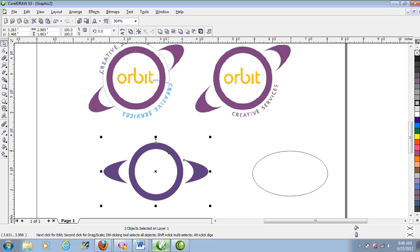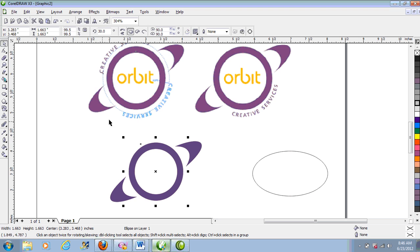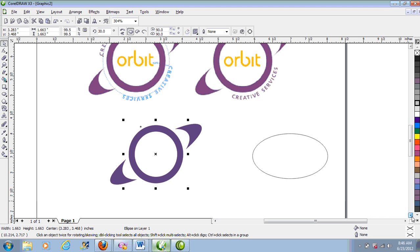Just take a look at the property bar while I'm trying to skew, and you can see the degree of skewness. That's 45, that's 30. It depends on how you want it. But in this case, I believe a skewness of about 30 degrees is what they used to achieve the sample object we are following.